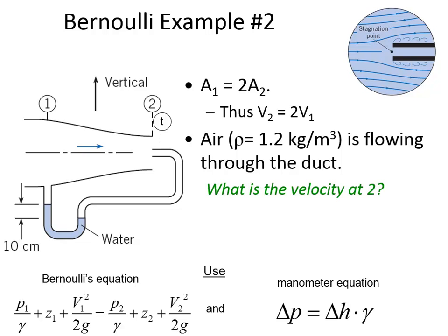It's going to be higher because, think about when it was not yet directed into the flow. Well, they're both going to be equal. And by the way, we're neglecting energy losses, so forget about pipe friction for now. These are close enough together that pipe friction effects are negligible. So they're the same, but then as we move this down and open it up into the flow, all of a sudden it's getting this extra boost of energy because the energy that was in the velocity head is going to be transferred into the pressure head, and so that would cause the water level to rise a bit further.